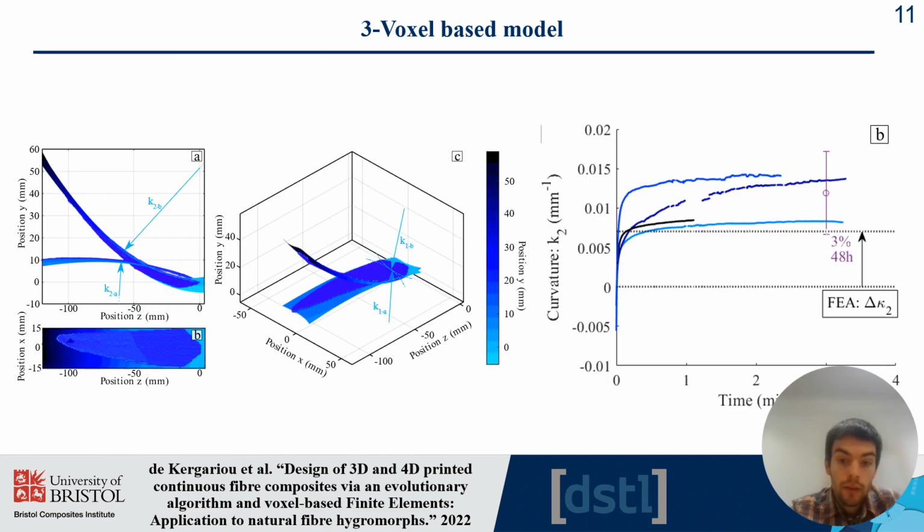So we conducted these tests on 4 different specimens with the same printed geometry, mimicking a leaf. You can see on the left the deformation that we obtained. We obtained the flat leaf that you can see for 11% relative humidity, and for 98% relative humidity we obtained the curved ones. This deformation showed very good qualitative comparison between the model and the experiment. We obtained basically the predicted deformation. However, regarding the quantitative deformation, we don't have the exact same value, and this is due to